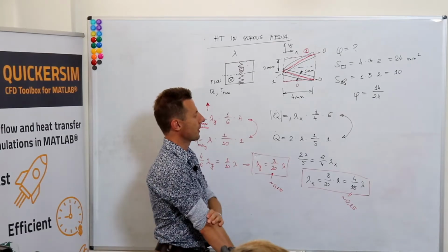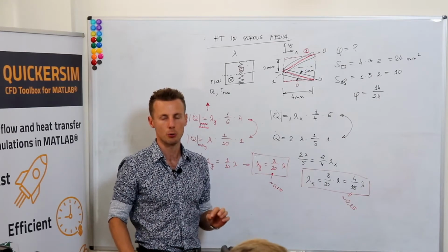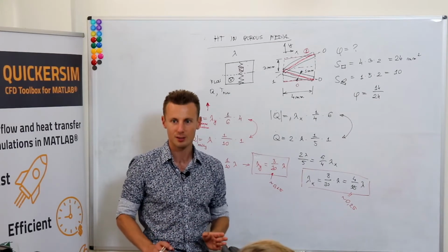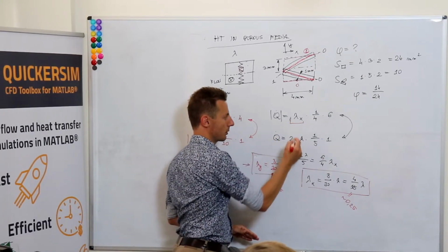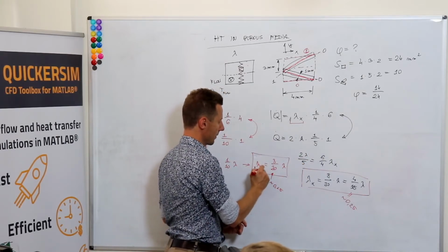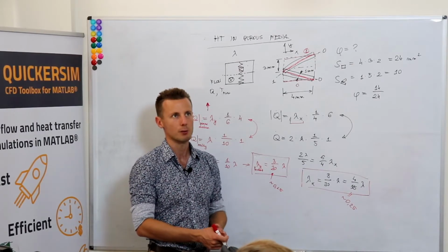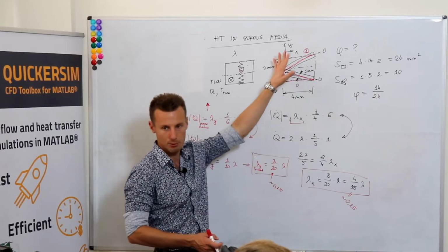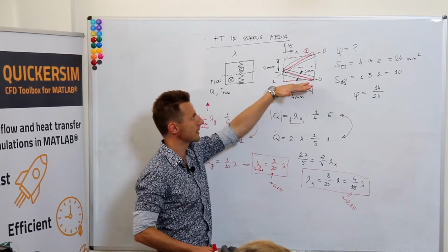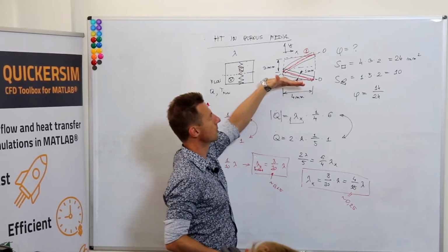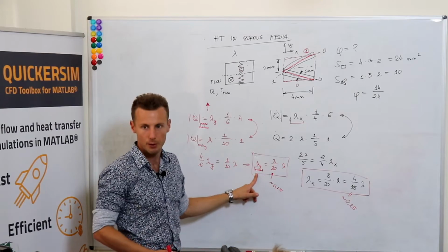Because we want to represent heat transfer in porous media as in every solid. So we want to derive such material coefficients that will give the same results in our simulations that real heat transfer in a porous medium of such a structure would give. So we are completely arbitrarily assuming that, okay, let's imagine we've got the temperature gradient in this direction to calculate our lambda y coefficient.